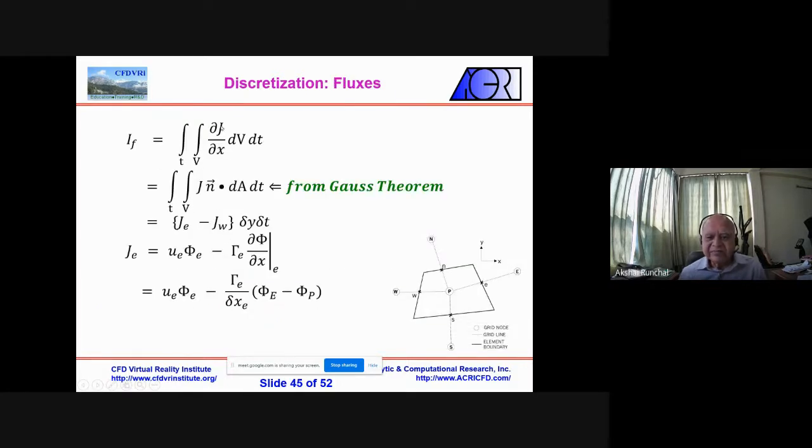And the flux term is basically dJ/dx, the gradient of the flux, okay? From Gauss theorem, we invert back. So actually you see that in finite volumes, we go back to the way we derive the equations to the root level, and we convert the volume back into the surface through the Gauss theorem, the inverse of what we did to derive the equation. So it's a much more natural way of thinking, okay?